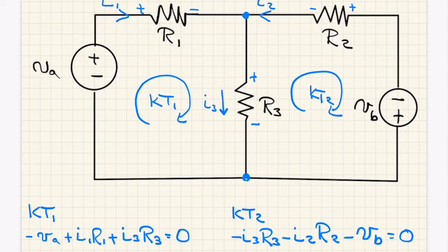Now I said I had a node to think about, so I have another node equation. Again, it doesn't really matter which way I look at it. If I take the top node, for example, then I'm going to see that the incoming currents, I1 plus I2, are going to be equal to the outgoing current, which is I3. And I'll use that equation. And so with that, I really have all the physics, the analysis of the circuit, done. From here on, it's really just solving equations.